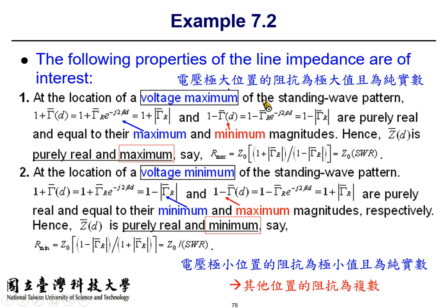Why do I draw this white circle? This means the reflection coefficient is smaller than 1. It's a more general case. So if you have some resistive load or resistance with some reactance, you will end up with a reflection coefficient smaller than 1. But it will be a circle on the complex plane. And actually this circle will be introduced as the SWR circle, the constant SWR circle.